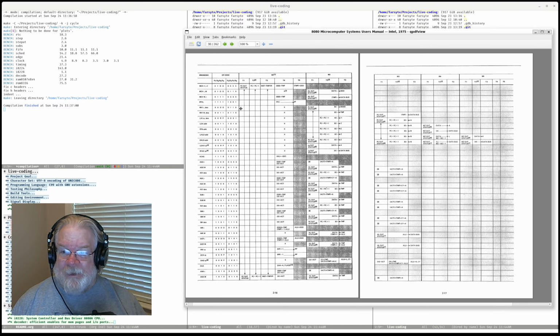Anyway, so move immediate data. We've got the opcode here. We will have a T4 cycle that does nothing in M1, but that T4 cycle needs to pick up an M2 cycle. And during M2, it's going to look like the beginning of M1 in some ways. We're going to send out the PC. We're going to give a status word that says status word 6. We will refer back to the table to see that that status word is here. Status word 6 is a